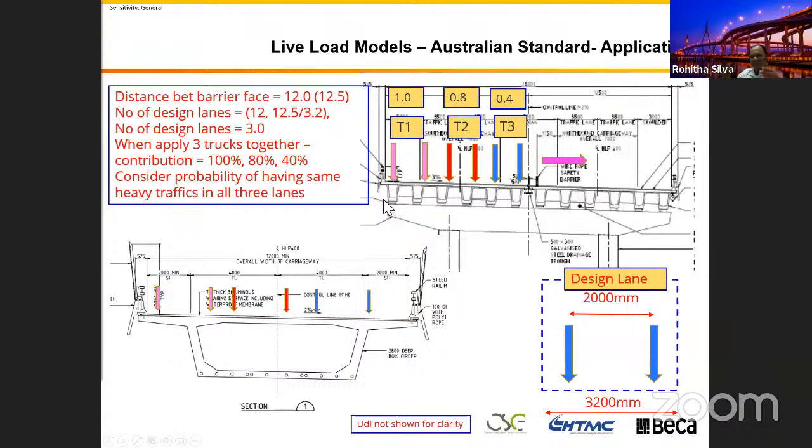In a particular bridge, different length, because when you develop the code, the loading system, to design 10 meter, 6 meter long to 300-400 meter long bridges, right? To have this M1600 or massive weight, if I put the truck weight in these 3 lanes simultaneously, to have that one is very rare. It won't happen that way. Because of that, the codes say, if you have a first lane, if you have only 1 truck in your bridge, use 100% of that weight. That's why I put 1.